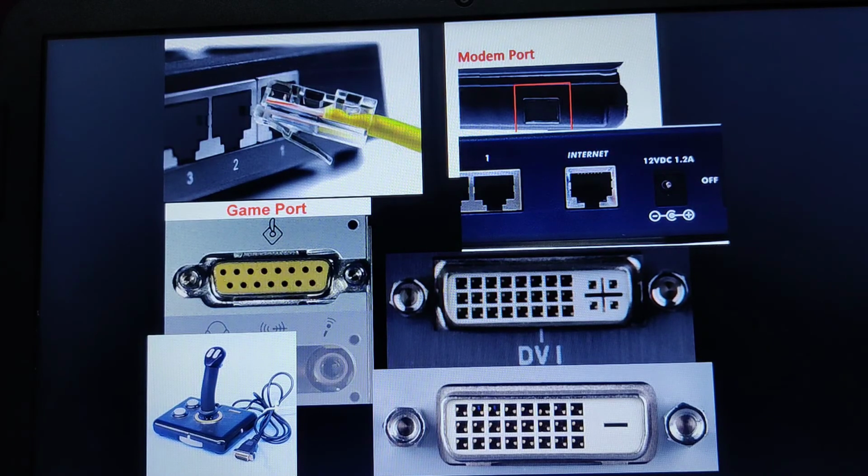Whereas we had one more port known as the VGA port. The VGA port was also connecting the monitor to the computer video card, but it carried only analog signals and has less picture quality compared with the DVI port. So when I make a connection between your TV and your computer system, I can't use the VGA port because it can only communicate analog signals. It cannot become an interface with digital signals. In such cases, I have to use the DVI port.